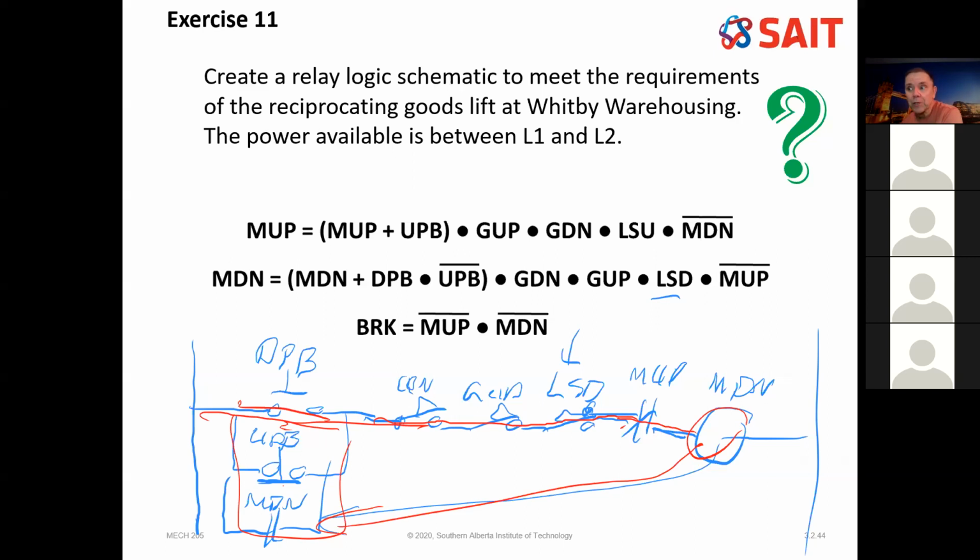It's got to do with the up push button. Anybody see what I did? You didn't put it in series with the down push button. Absolutely. See, I did it in parallel like it was an OR, right? Oops. I looked at the logic and said, wait a second, that's not going to happen. So yeah, I got to take this out.